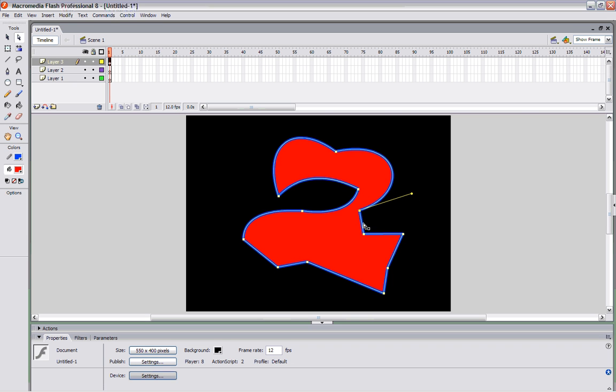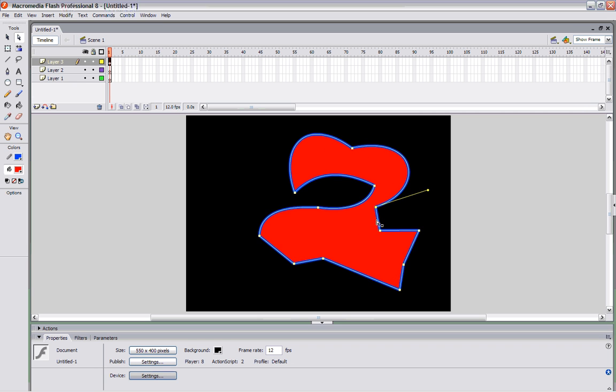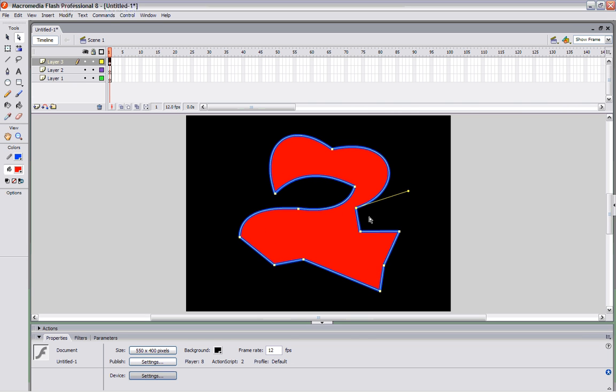How do I get this to be different? Okay, notice if I move it, it's just going to move everything and I'm not getting a curve like we did before. Okay, the way I get this to curve, if I want to make this line curve, is I go back to the selection tool and that's where I get the ability to curve that. Okay, but the sub-select tool is not going to do that. That goes in at a different layer and allows you to play with the pick boxes. Now I have this, and I can go in and I can get a Bezier curve. That's called a Bezier curve. I can select this one and start to play with that if I want. So this gives me the ability to really get a more complicated curve going.